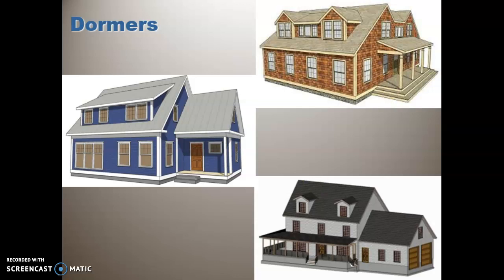So that's it then on the types of roofs that we're looking at. We covered the fact that you're going to have either trusses or rafters, and it's going to be a specific slope that's going to be dictated by the rise and the run, the horizontal run and the vertical rise. The example I gave you guys was 7 rise, 12 run, 7, 12.